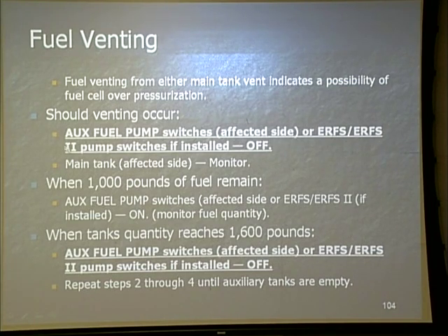Fuel venting. Again, what would happen if I didn't select a main tank to identify which side is the problem? What if I just reached up there and turned off all my auxes? Have I created a problem? Not really, because I can still troubleshoot it and figure out which one is venting. But what I possibly have done is saved the aircraft from the possibility of structural damage. Because if we get into that fuel venting caused by what? The transference of fuel from the aux tanks to the main tanks,